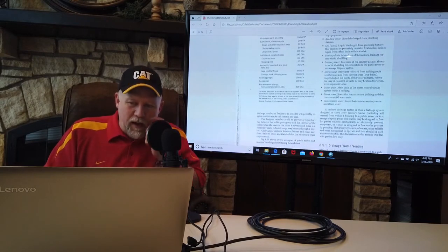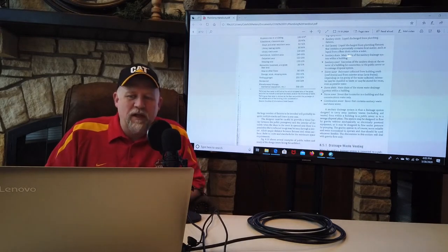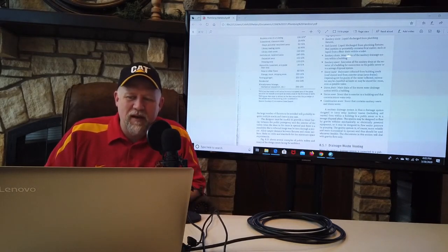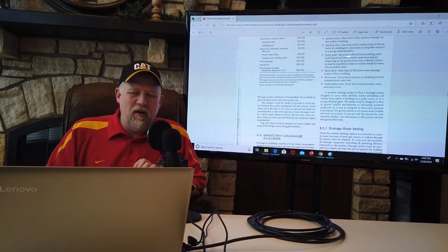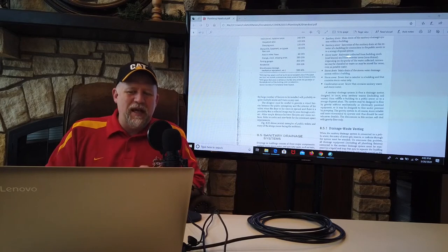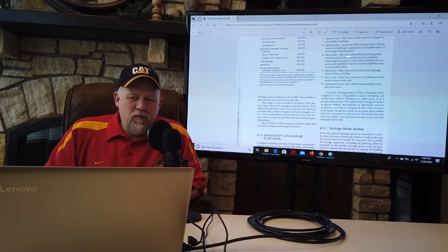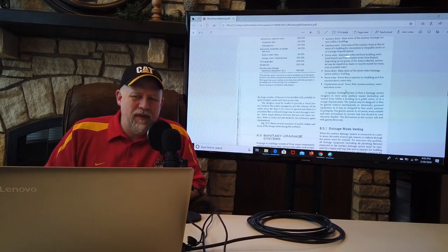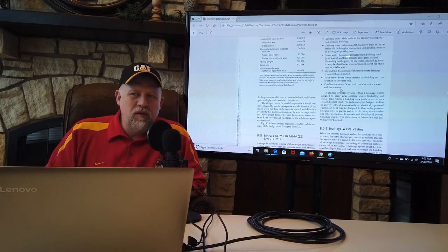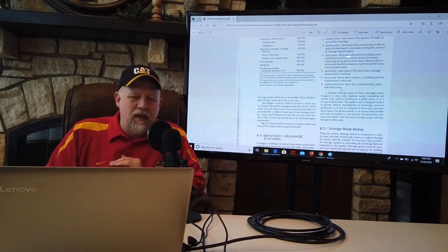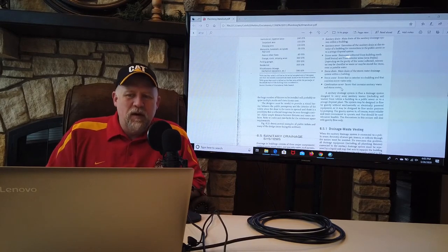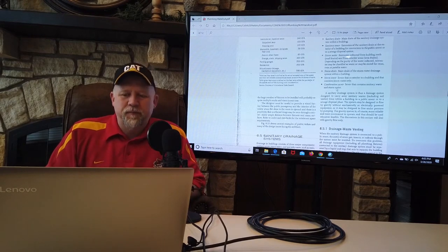Same way with stormwater. Stormwater is rainwater collected from the roof drains and exterior areas like parking lots. A storm drain is the main drain within the building, and then the storm sewer is on the exterior of the building that only contains storm water. Storm sewer and sanitary sewers are different things. Storm sewers can only have rainwater, and they can discharge to grade or to a stream or something along those lines. Sanitary sewer has waste in it, needs to go to a sewage disposal system.